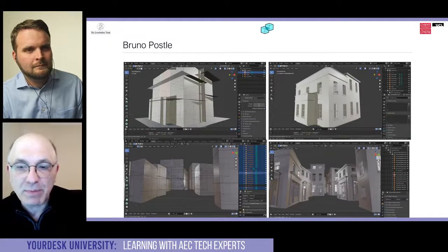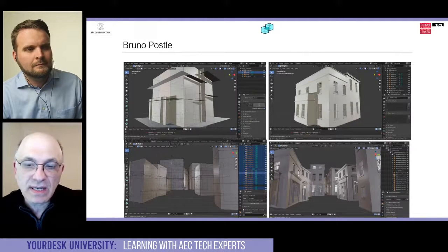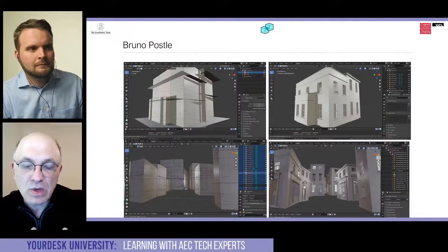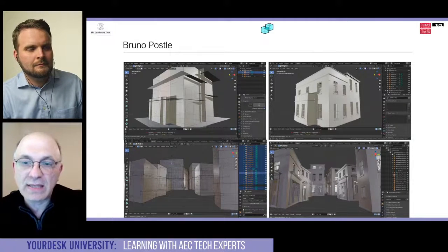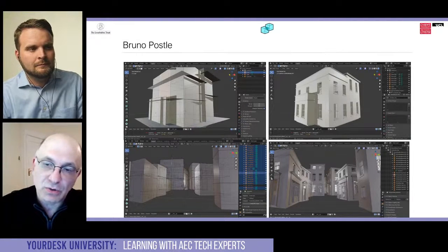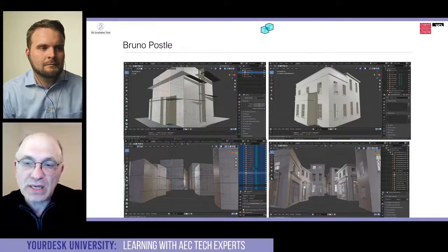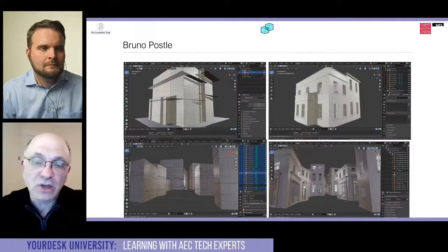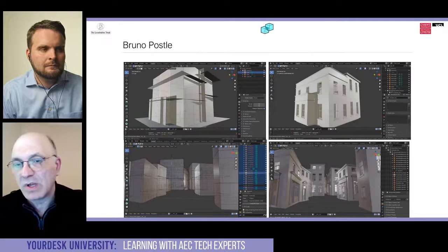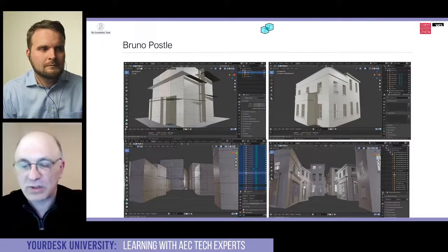And that becomes really powerful because let's say you're designing a hospital and you sliced it up into rooms, and then you assigned one room to be an X-ray room. That's where the X-ray machine is, and right next to it is a waiting room, right? That wall needs to know that it is between an X-ray machine and a waiting room, because it will probably need to have some kind of lead paneling or something like that to protect the people in the waiting room from radiation.